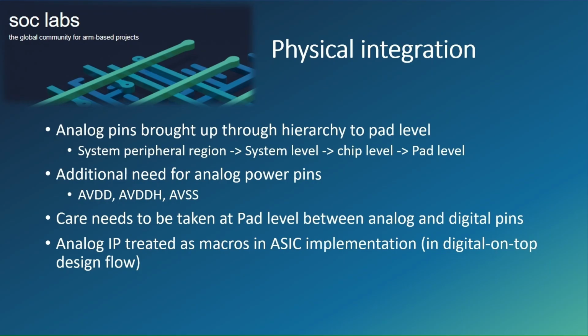In terms of physical integration, we've had to bring analog pins up through our hierarchy all the way to the pad level, including changing the analog power structure. In the way that we do this, you can separate your digital and analog domain, or you can try to combine them as well. And this is where care has to be taken. Obviously, we're doing this as a digital-on-top design flow, so all of the analog IP is going to be treated as macros.